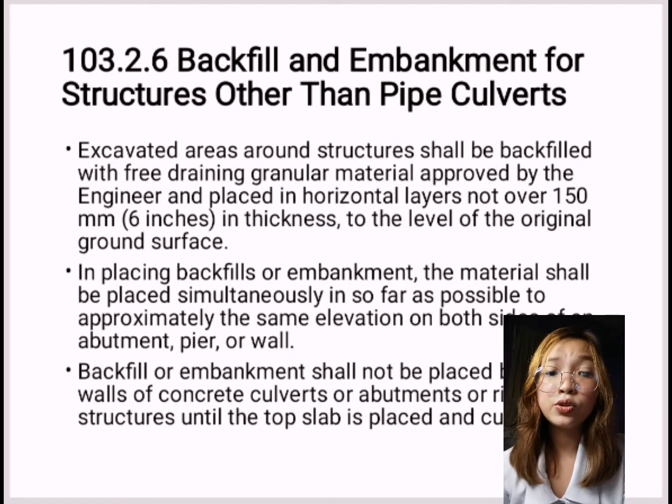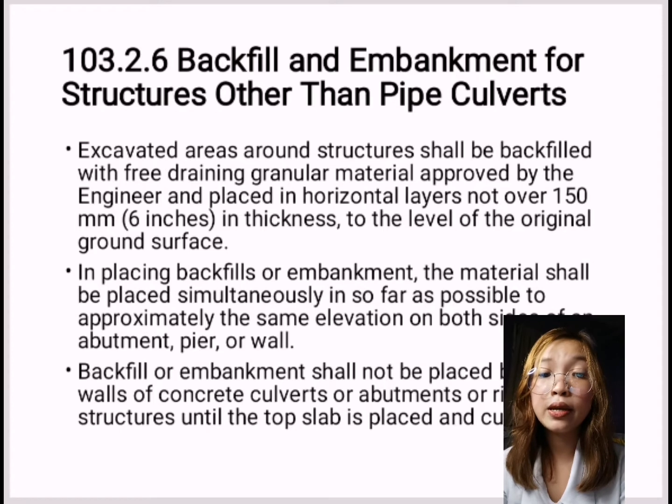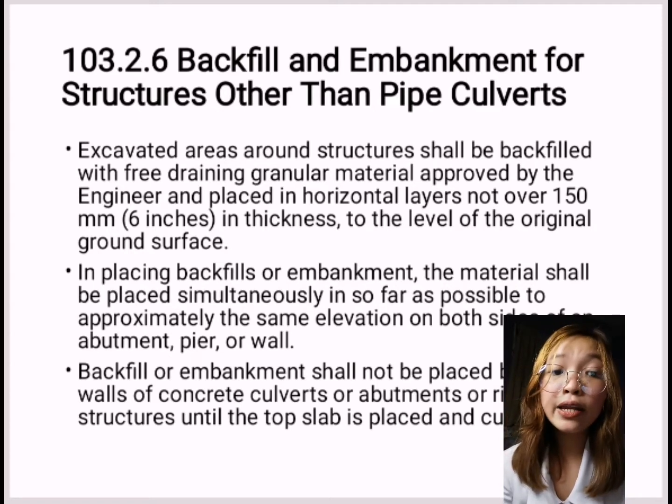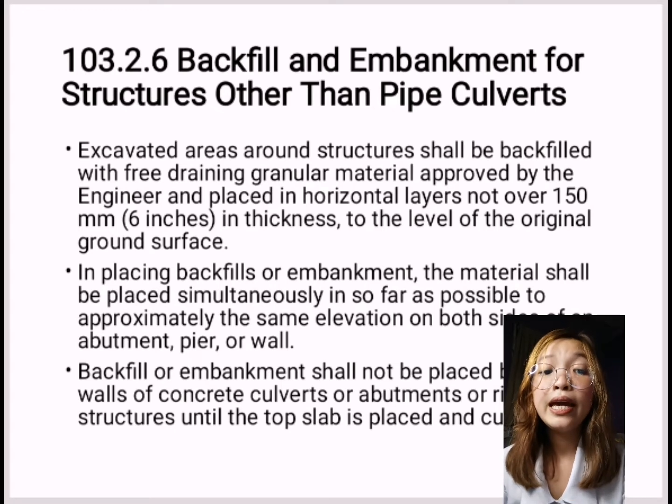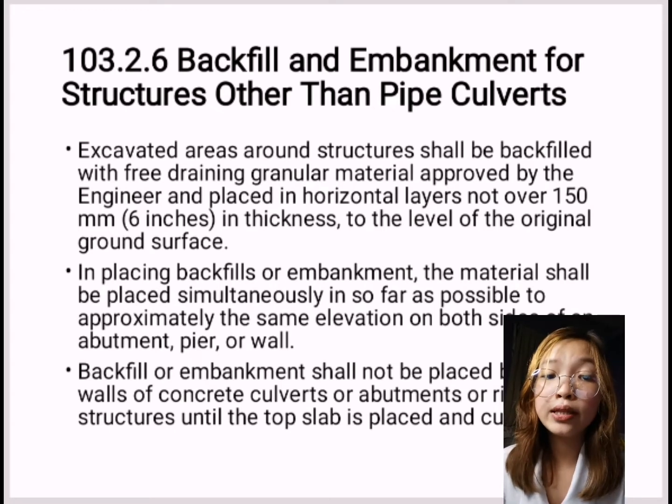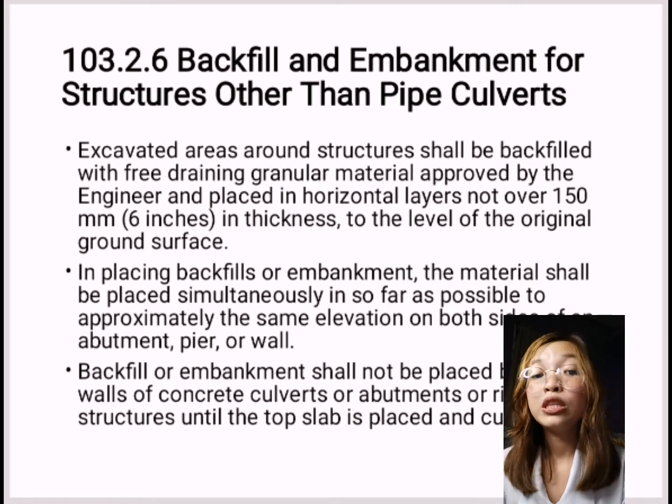In placing backfills or embankment, the material shall be placed simultaneously in so far as possible to approximately the same elevation at both sides of an abutment, pier, or wall. If conditions require placing backfill or embankment appreciably higher on one side than on the opposite side, the additional material on the higher side shall not be placed until the masonry has been in place for 14 days or until tests made by the laboratory under the supervision of the engineer.